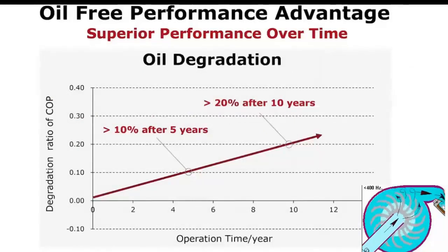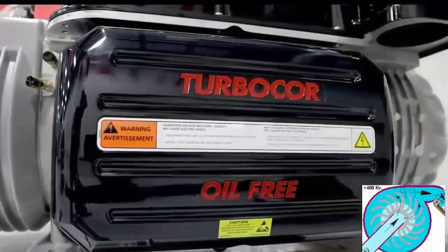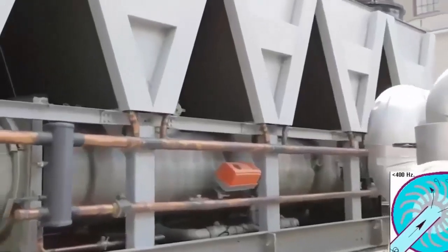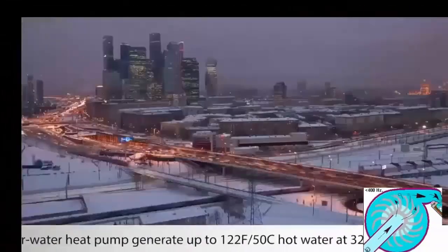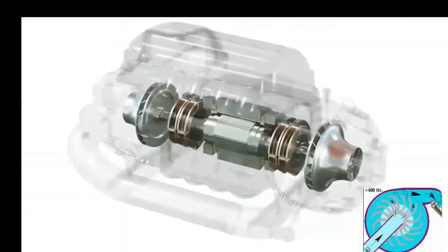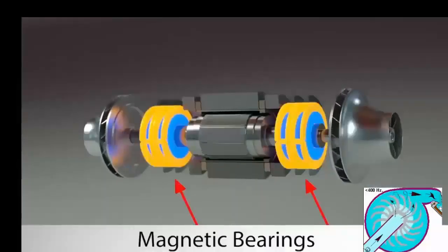The fact of not having oil will reduce the chances of failure when we use bearings without oil, and we will also increase performance. We will create one more reliable and higher performance machine. This technology is based on the use of magnetic type bearings, also known as magnetic levitation bearings. This type of bearing is based on the principle of electromagnetism by which the compressor shaft rises, and once the compressor shaft is above it starts to rotate.